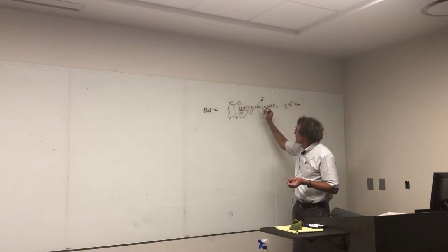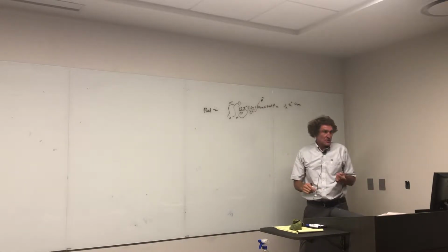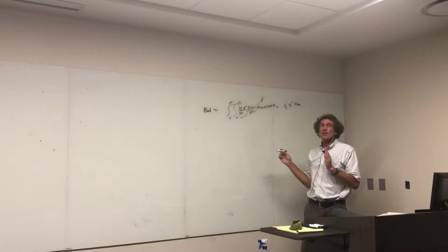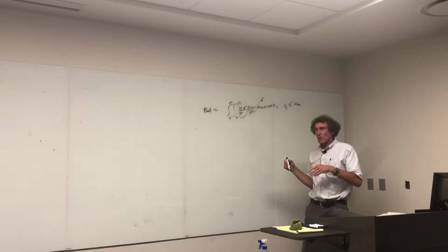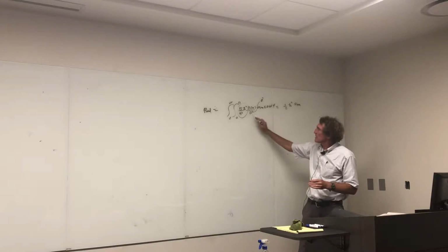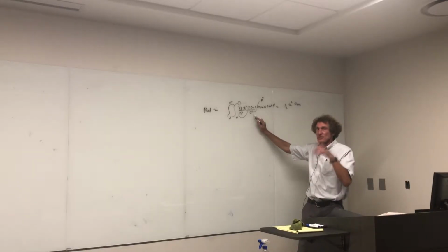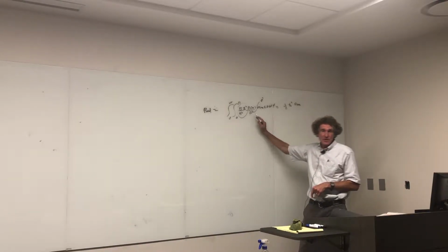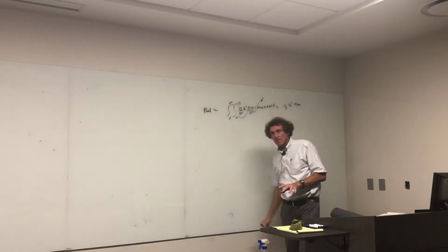This right here is f of theta, which is, remember, the squared value of the cosine of beta L over 2 cosine theta minus beta L over 2 minus cosine of beta L over 2, all over sine theta. Something I'm going to tell you: when you square that, you have a sine theta here, but you have a sine squared down here. You're still going to have a sine theta downstairs when you do the integration. And that almost always means go to the numerical stuff. And he has it in MATLAB.